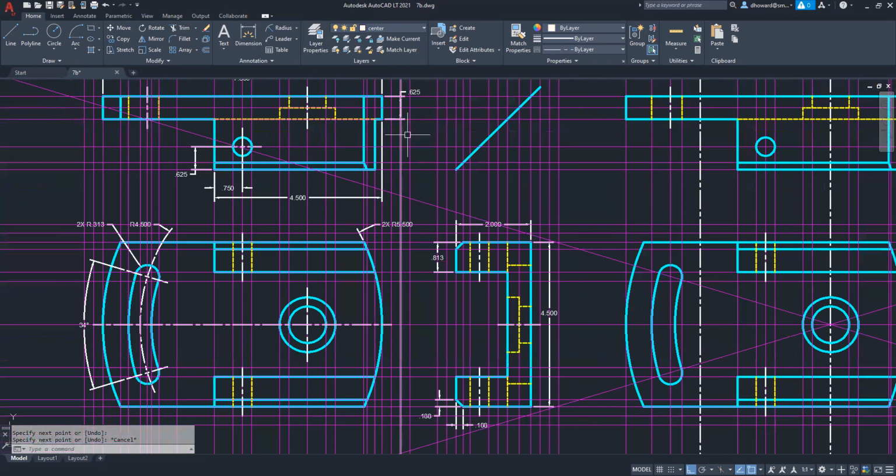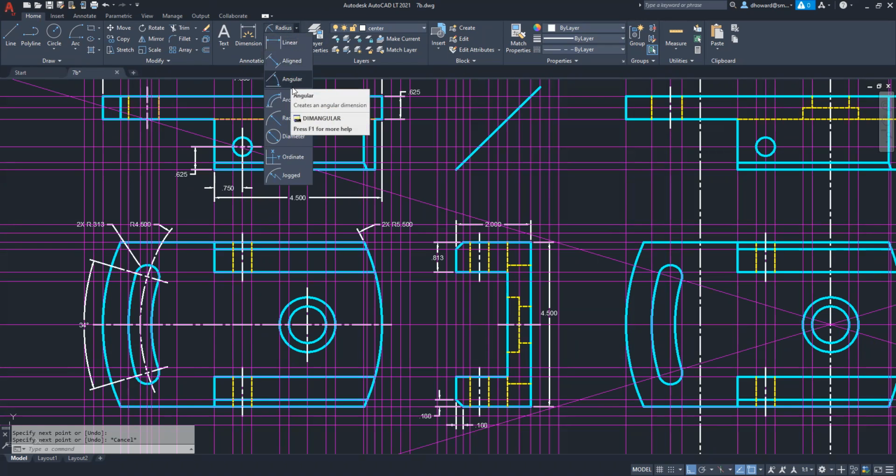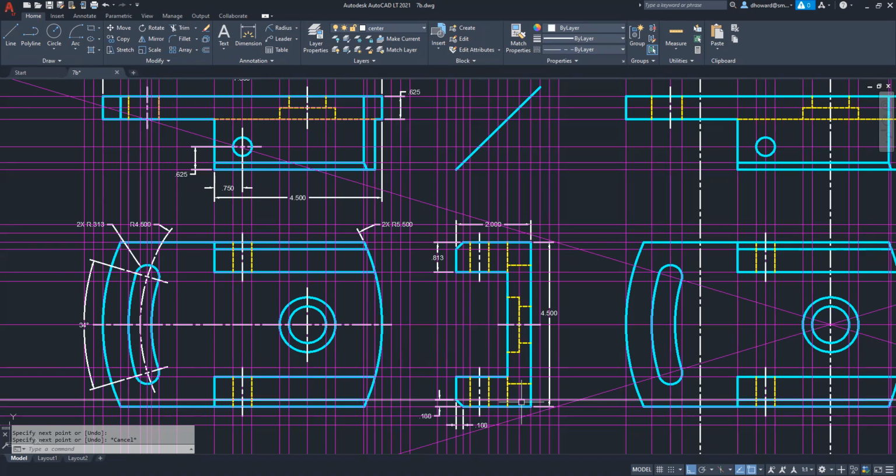And the center line going through the arc itself, as you can see, is just that 4.5-inch radius that we made. And then you would dimension to it using the arc measuring, angular measuring dimension. Do note that I did give it its size by specifying its radius and specifying that they were both the same radius on both sides, because there are arcs that are tapered, but this one is not.